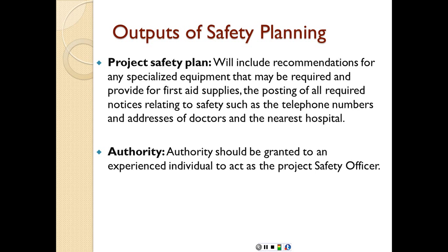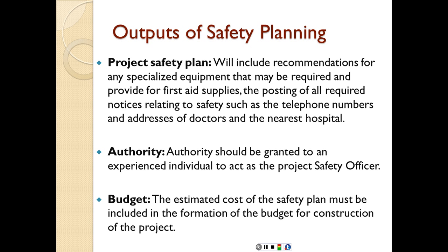The authority should also be granted to an experienced individual to act as a project safety officer, who is going to be responsible for maintaining the safety measures on site. And finally, the budget. The estimated cost of the safety plan must be included in the information of the budget for construction of the project. Some owners require that you post that as a percentage of the total project cost, let's say 1% or 1.5%, and they're going to reimburse you for that so that you don't cut corners when it comes to an important issue such as safety.